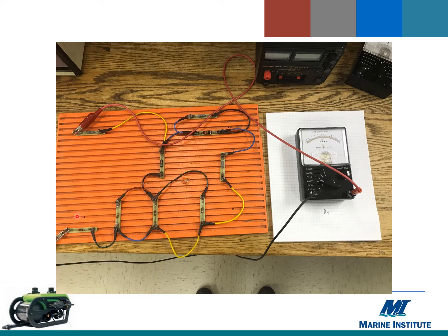And so this terminal and this terminal is where we plan to connect VT, and so that is where we will measure RT. The connections using these quick clips are similar to the lines drawn on the diagram for figure 6.1. So this clip here, these two resistors, left end connected together, right end connected together, so they are in parallel. That parallel branch feeds into our 8. Our 8 is connected to the bottom of this parallel branch. Resistors 3, 4, and 5 are in parallel. The tops are connected together, the bottoms connected together. Current flows through the wire and through the circuit.